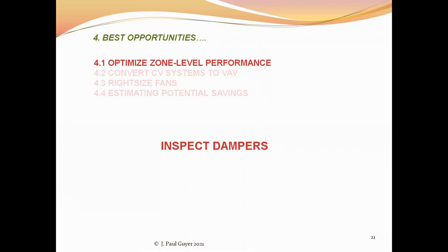And also, something that can be significantly cost effective is to have the entire system or the floor you're dealing with have the system rebalanced. In other words, hiring a testing and balancing contractor to come in and rebalance the system based on the occupancy and the activities that are going on in the spaces today.